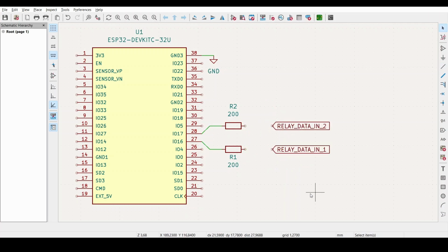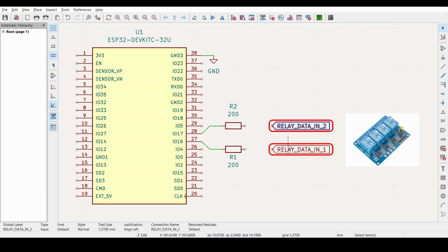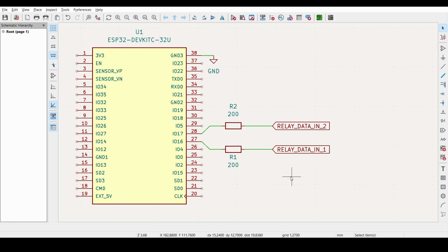If you prefer, you can also connect these GPIO pins to the input pins of your relay modules instead of LEDs. That way, instead of turning small indicator lights on and off, you could switch real devices like lamps or fans using HomeKit. The code works exactly the same, only the hardware changes.